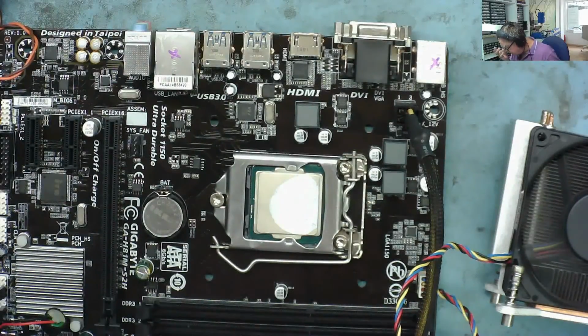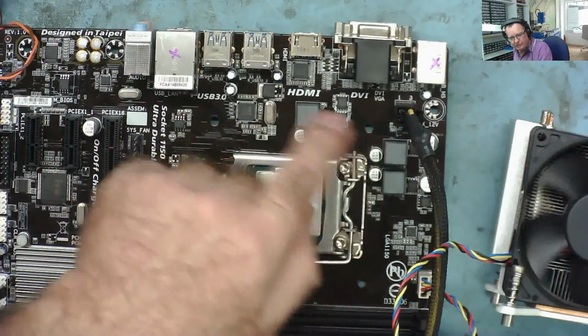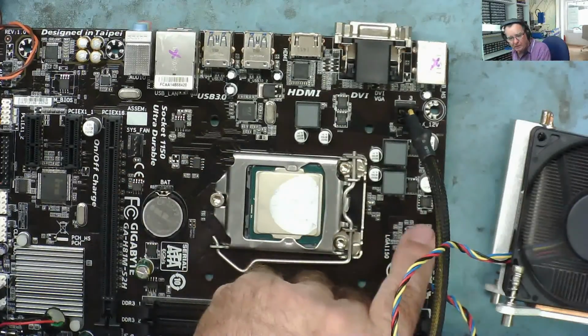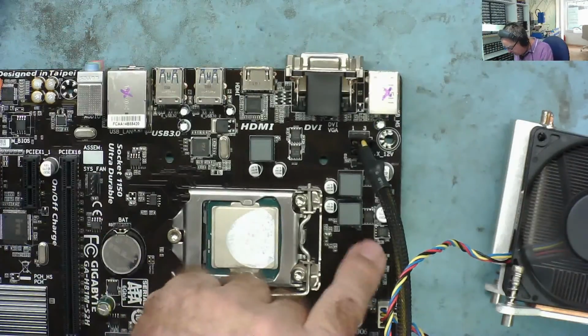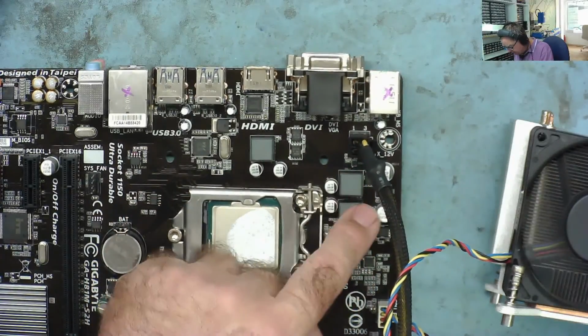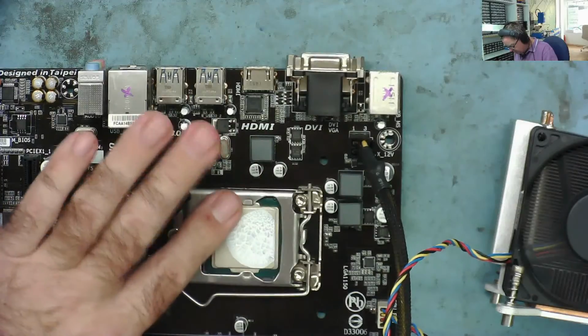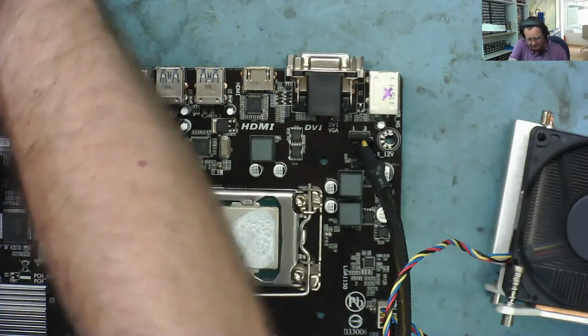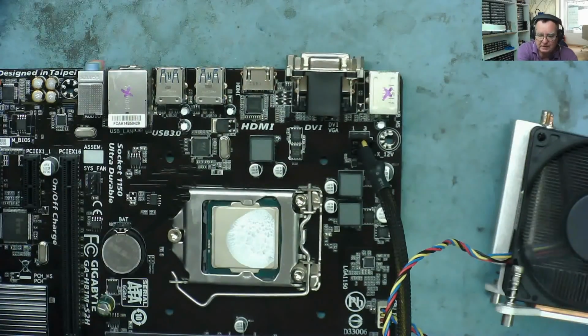Has it got any V-core? The easiest place to check is on these inductors if we just turn it upside down. Well, the other way is to check on the MOSFET. So there's a pair of MOSFETs and a capacitor there. That's one phase, and this is another phase. Yeah, this is a different supply. This is cold, so I'd say we haven't got any V-core. I'll just zoom down, and then we'll make some measurements.